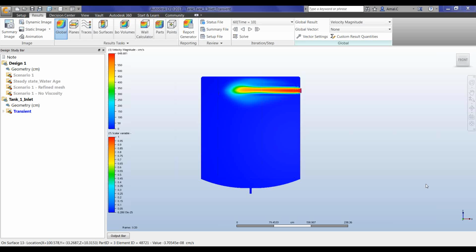Exactly. So if you're mixing, for example, 3 different cases, you have to see your density. Is it changing according to pressure, to temperature, or is it changing according to the equation of state? So it depends. And then you have to calculate your density and gas constant for your mixture. It should be made manually, actually. Okay, good point.